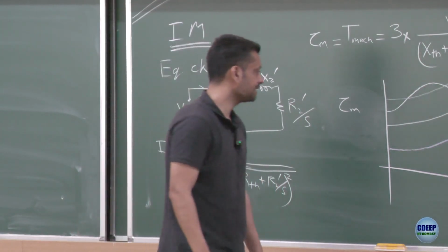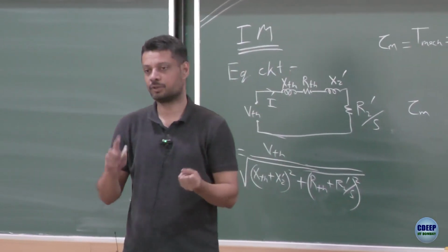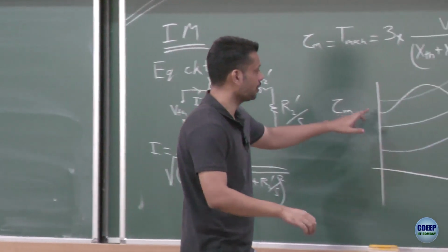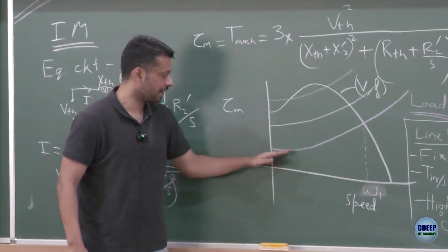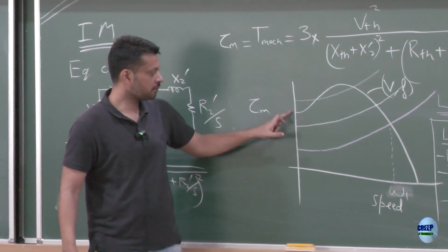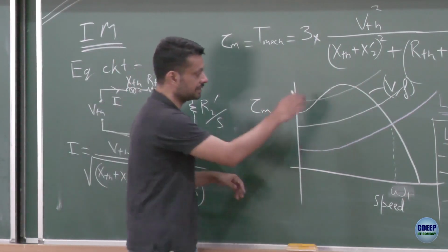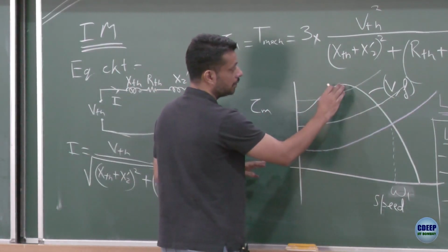Okay. Good. Excellent. This is the correct answer. I think this sort of sums up everything. So the problem is, initially your motor characteristics is like this, your fan is like this, right? So both are happy. You started even at lower speed. This point may be less, right? If you apply lesser voltage, this is how the motor characteristics change.